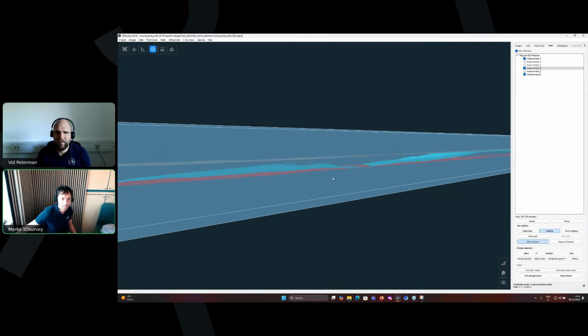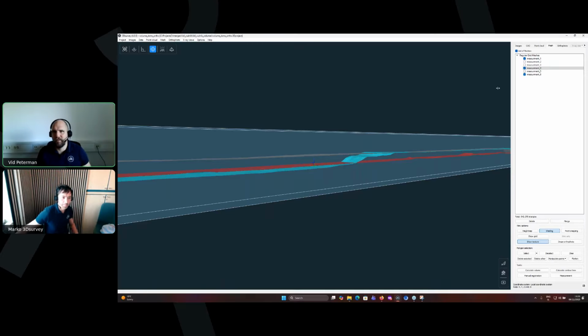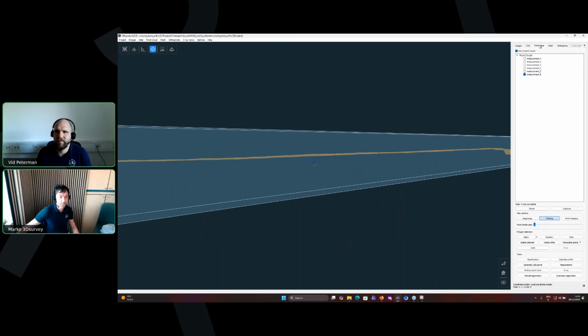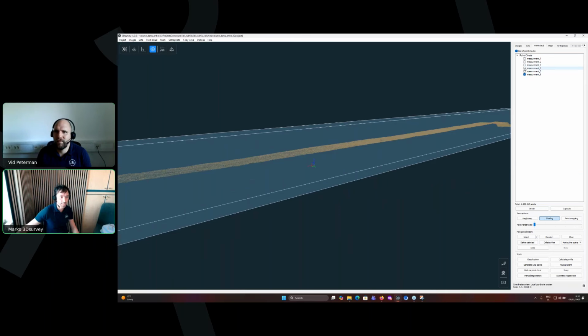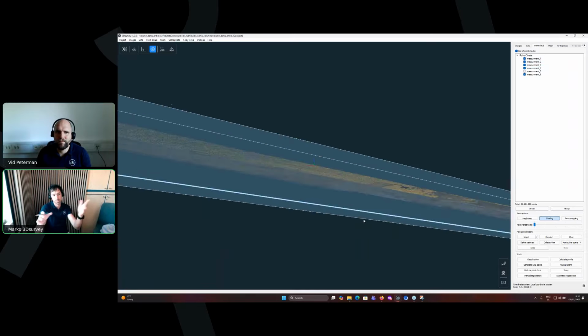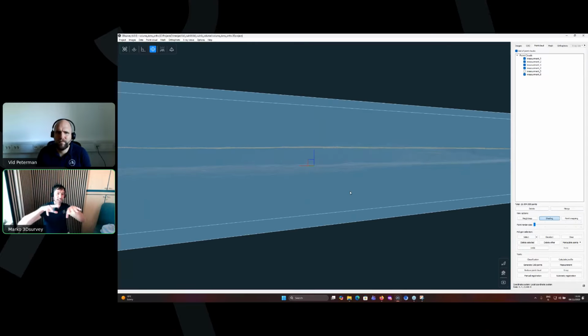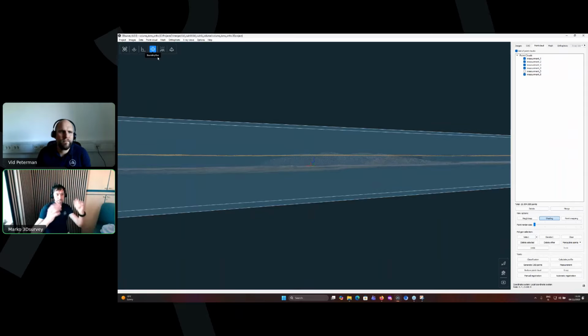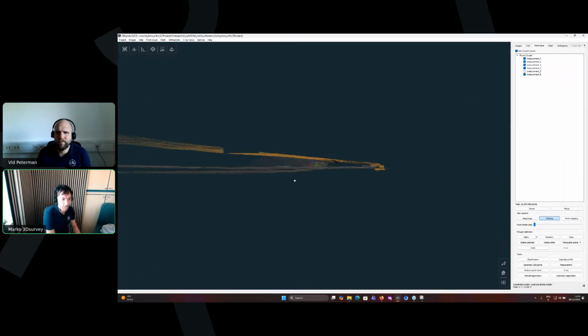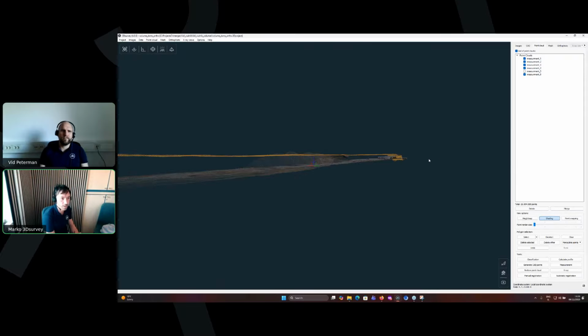Here we are not limited to 1, basically you can put in as many as you want. And you can even later combine them, so merge them into a single one. If you have point clouds close to each other, you can merge them together. Or if you have one photogrammetry point cloud and another from the scanner, from indoor, you can merge them into the same one and calculate the surface together and so on.